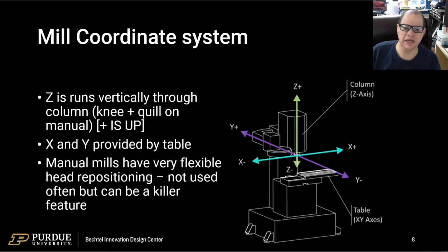So all in all, it's a powerful package. It's very flexible in what you can use it for, and it's a very rigid structure which can basically do a fantastic job of producing drill patterns and slots and holes and corners and pockets and facing a block, i.e. taking a raw piece of stock and squaring it up. And if you put a rotating table onto the bed and bolt it down, you can even do a lot of lathe type operations of doing radii in corners. All without removing the workpiece from the bed, which is a colossal pain, which we'll talk about more in work holding. But work holding is one of the 2 main problems in machining. You have